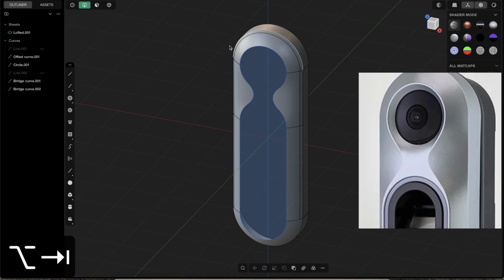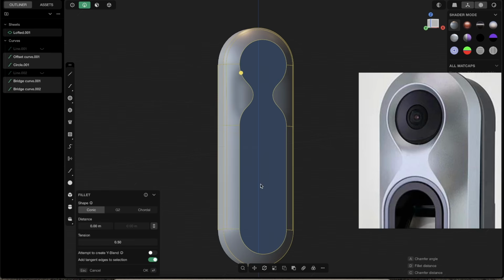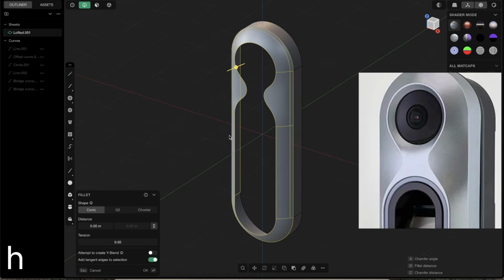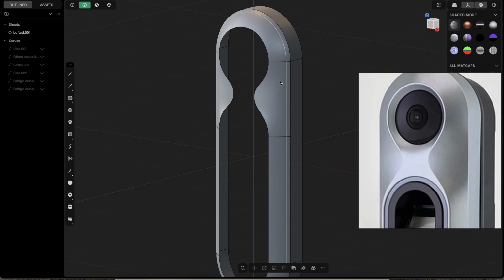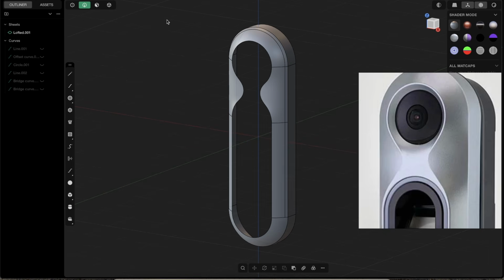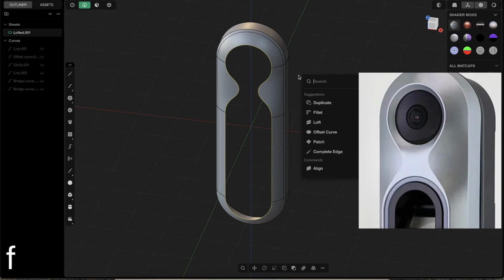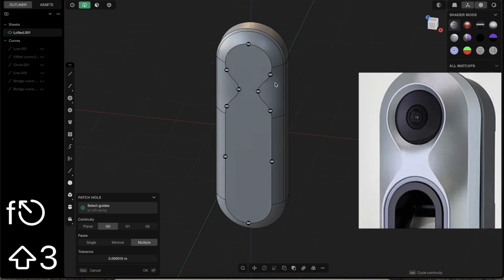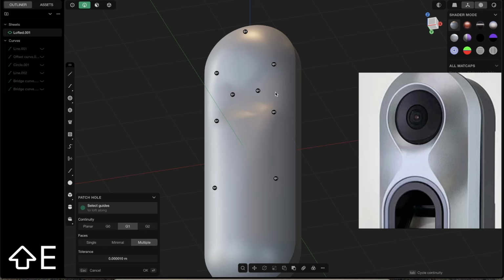select, edge mode, select everything. This way our blue curves will be selected, and hide them for now. And first of all, let's close everything with the flat surface. Very simple, edge mode, alt, click. So you select this whole loop and now just patch it. So again, press F, patch, right? So just patch it and obviously leave it as G0.